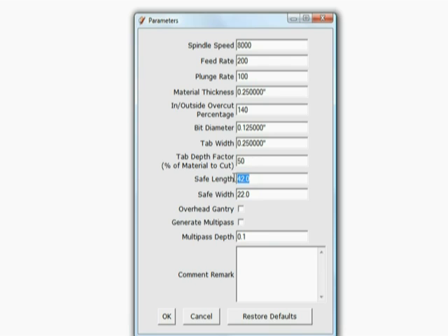But the length, now I told you that I had a 48-inch long sheet of material, but I'm putting in 42. Again, this is dependent upon your machine's demonstrated capacity. I know that with my original flat printer, if I put in a 48-inch length of material, I had to lose approximately 6 inches of material. I believe it was 2 inches on the front of the sheet, 4 inches on the back, and the reason is because I had to have that foam stay in between the pressure roller and the drive rollers, so that it would get traction.